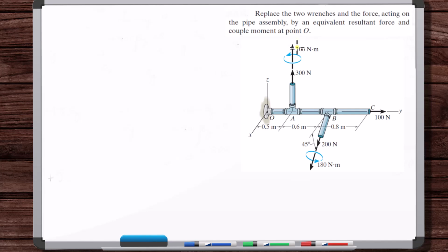What we can do is, let's just analyze this from what we understand. So these are free vectors, right? This is the component of the couple moment that was parallel to the force at, let's say O. Let's say we're talking about O at any point. You can do this for any point, but we're looking at point O, right? We moved the force, the resultant force, off to get rid of that perpendicular couple moment component. Then we just took the parallel couple moment and brought it to the force. Well, let's just bring it back. Let's bring these two back.